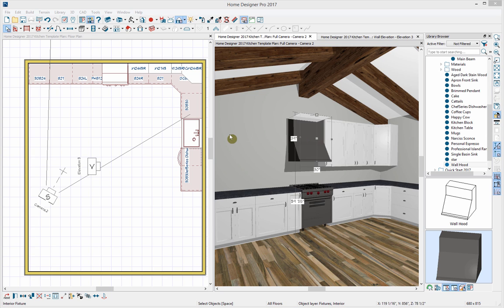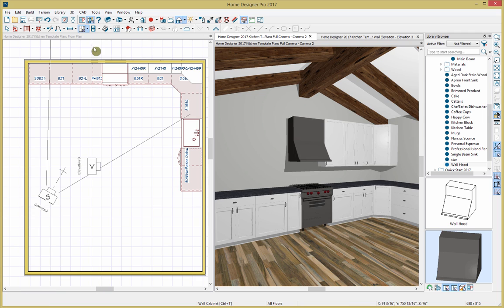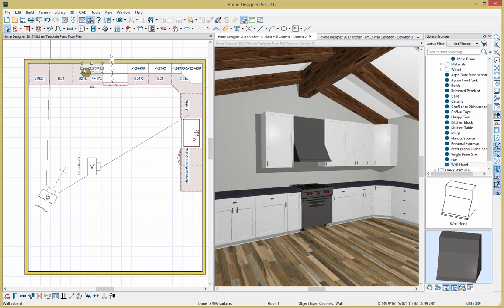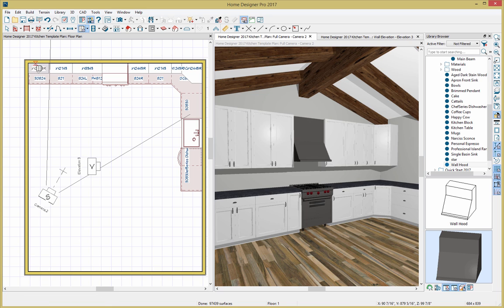Let's finish out this corner wall area by placing those additional wall cabinets. So we'll click on that cabinet tool. You can click on in plan view and then on that tool, and then I'm just going to adjust it. So I'll grab this cabinet and pull it out. And I forgot to mention that when you adjust cabinets, you can also see that if you expand it out, it will automatically bump it to a double door. And I'll just grab that, select it. You can click tab to grab that cabinet specifically, and then we just have one more wall cabinet to place over here in that corner, and I'm going to bump it back over, and then it places that filler in there. And then let's move back over to our adjacent wall.